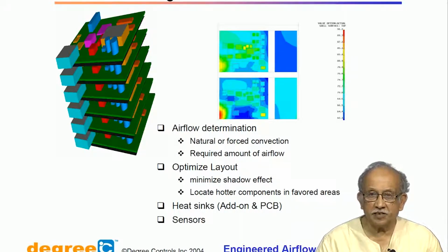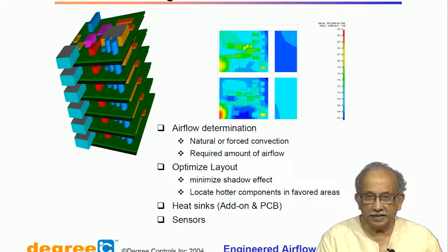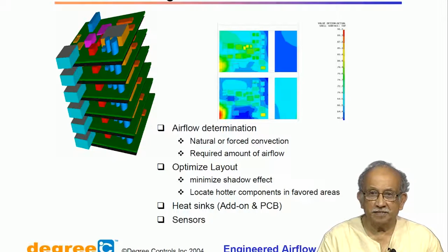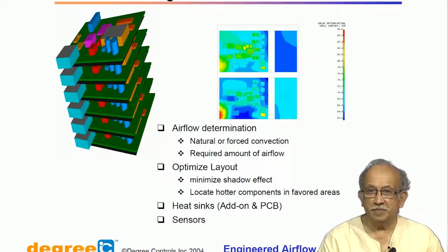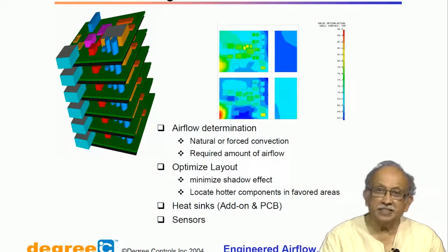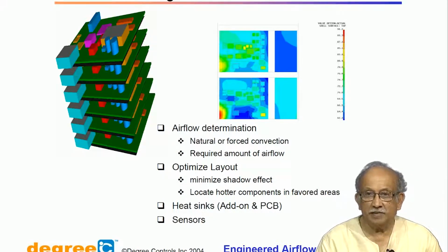If you put the hottest components at the beginning of the airflow, the cold air enters, and it looks like they get the maximum advantage, but the disadvantage is that the air in the trailing path is likely to be heated up. Now, that may be exceeding the inlet requirements for the next component. It is a little intuitive and then counterintuitive also.